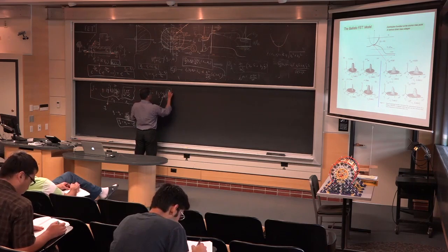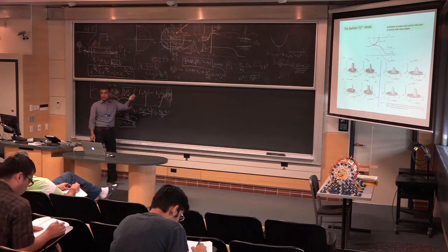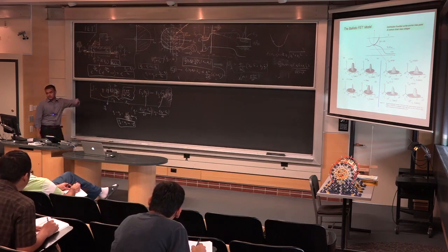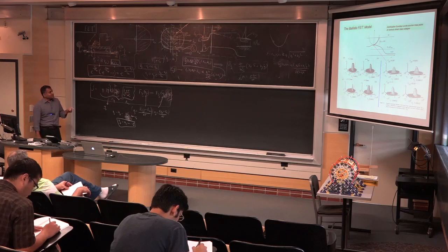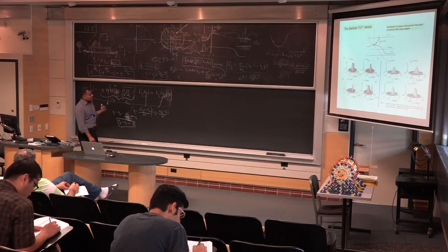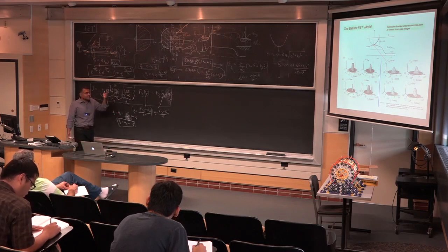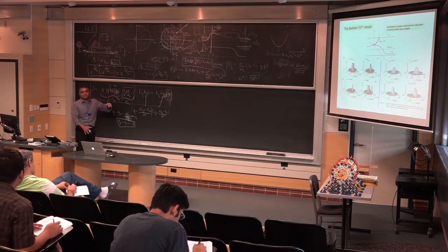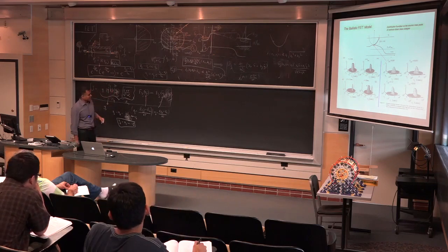Okay. And the unknown is just what is this eta sub s? If you know that, you have the answer at your fingertips. But basically, it has all the answers in it. And we'll see now that to find that eta sub s, you need to know drain and gate voltages. And there's an equation that gives you that. And once you get that equation, the problem is completely solved. You just plot it and all that.